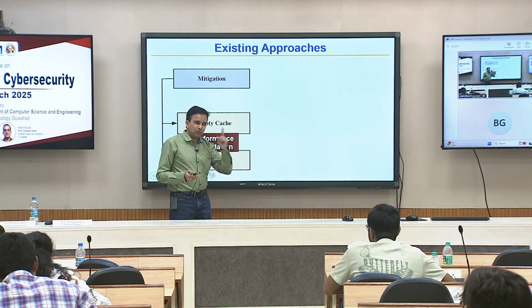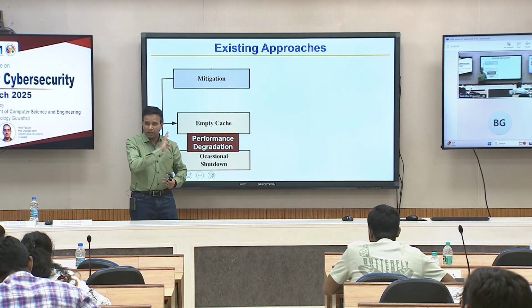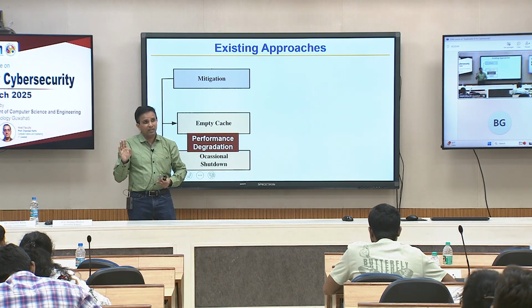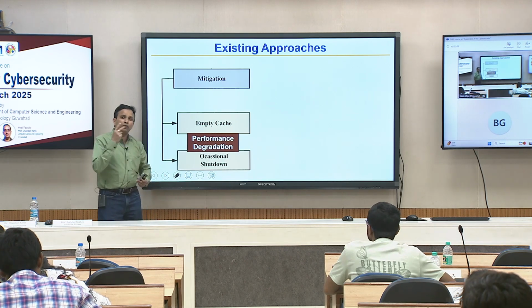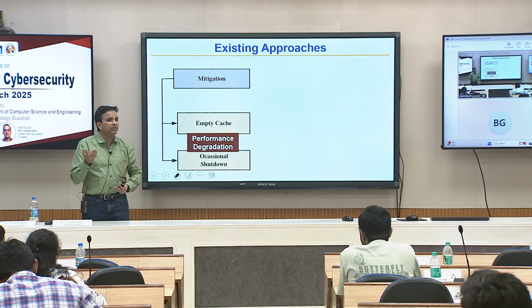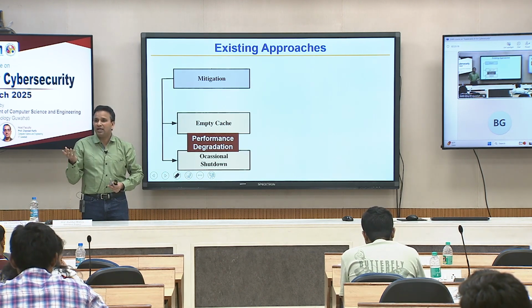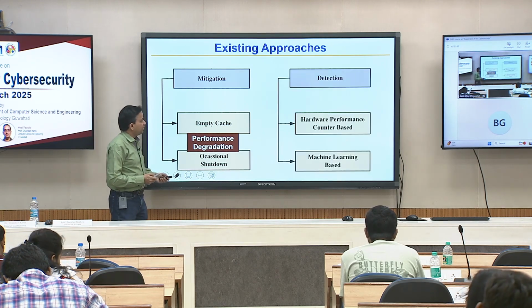So, you have to wait at least one cycle, maybe 2, maybe 3, depending on the size of the pipeline after every fetch. So, you cannot fetch an instruction every cycle if you want to disable branch prediction. If you have to wait at least one cycle every time, that is a slowdown of half. If it was operating at a gigahertz, now it is operating at 500 megahertz effectively.